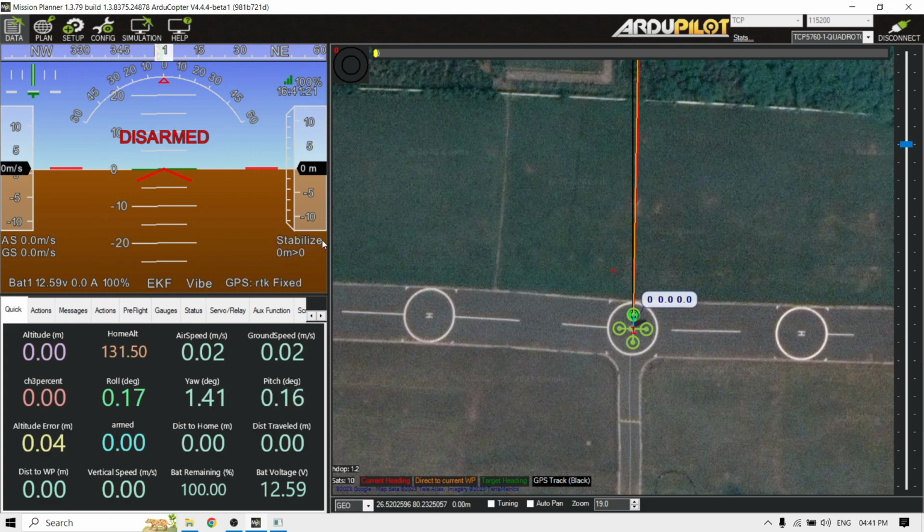This is the flight mode, in the sense of how our drone behaves. So as of now it is in stabilized mode. So if I start taking off, it would be stabilized, it will always balance. The stabilization part, the drone's control algorithms will take care. But what we need to take care of is the altitude, the front, back, roll, yaw, these things we need to control, and we would have full liberty for that. And I guess apart from this there's nothing much.